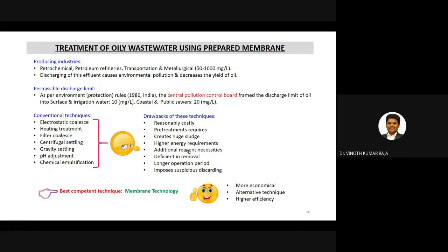However, the treatment cost is further lowered by choosing microfiltration membranes, since they do not require a higher transmembrane pressure, and they can provide a higher flux than ultrafiltration membranes. So our preferred membrane is the microfiltration membrane, which can be operated at a lower applied pressure and can also provide a higher flux.